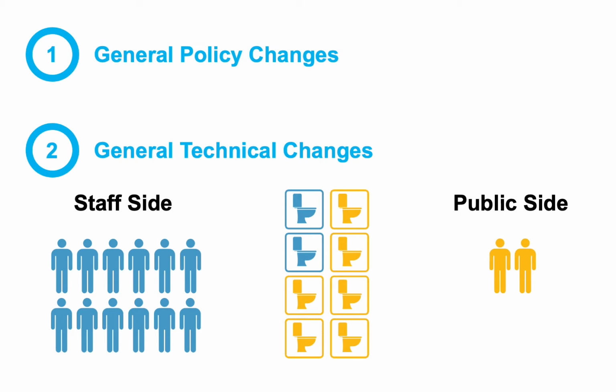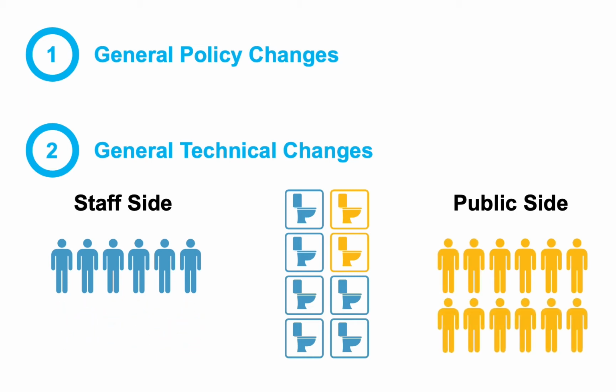In the updated design guide, staff and public restrooms are allocated based on the occupant load. For floor plates that provide for staff functions and have very little public interface, more toilets may be allocated to staff. On other more public floors, such as court floors, more toilets may be allocated to the public. This allows the building core to expand or contract as necessary to accommodate these fixtures. In addition to this change, court unit executives are now allocated a private restroom. However, the space for this restroom should be offset from within the court unit space envelope.